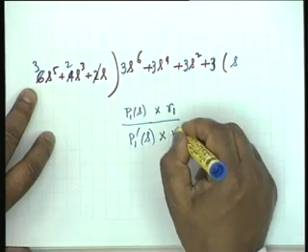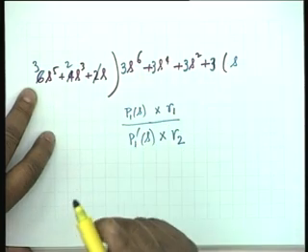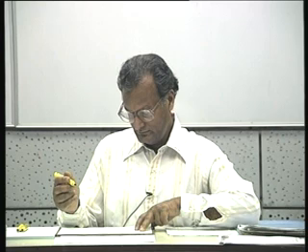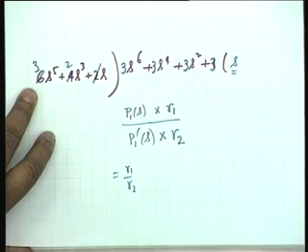I could multiply this by another arbitrary positive constant R2 without affecting the signs of the quotients. Is that clear? It will not affect the signs of the coefficients of the quotients. All that it affects is the value of the quotient. What I was saying is that if we divide that s^6 plus s^4 by some value and carry out the division, then further subtraction may introduce a negative. No, why should it? It will depend on the value of the quotient. It will not affect. You see, this is simply R1 by R2 multiplied by whatever the CFE is. But R1 by R2 is a positive number, so it will not affect.